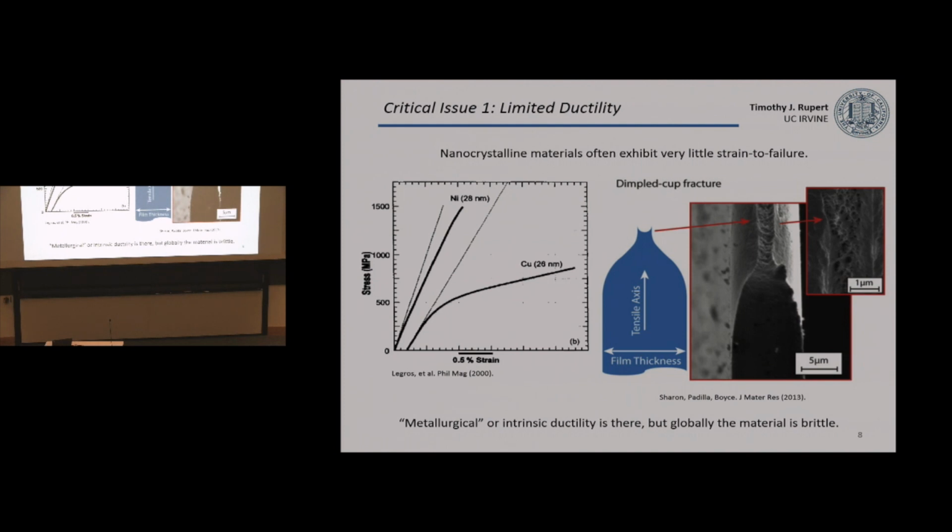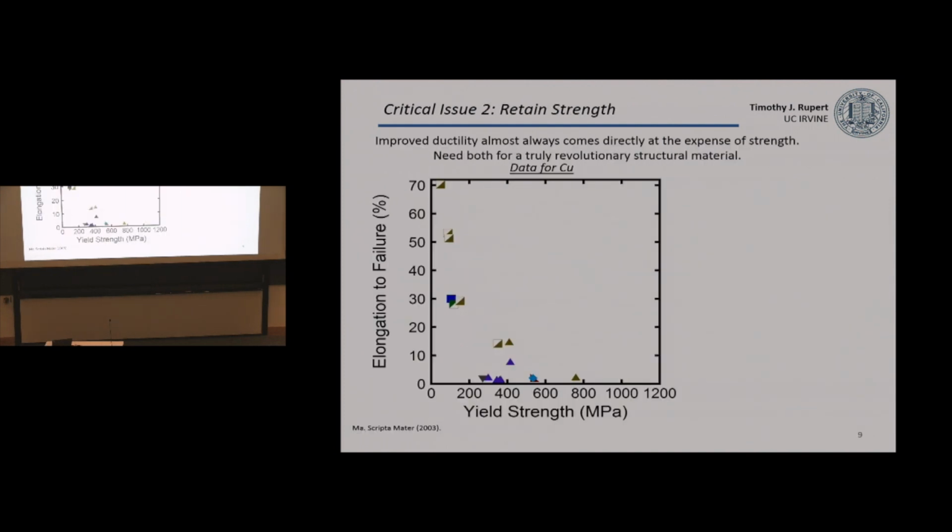Okay? So when we do this, we have to keep a few other things in mind. We have to be able to retain the strength of this nanocrystalline material. There are plenty of ways that people have come up with wacky ways to improve the ductility of nanostructured materials, but they always come at the expense of strength.